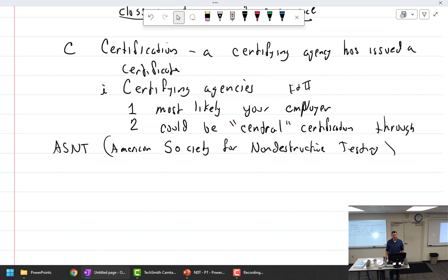Would you find NDT more in general aviation or in every type? Across the board. I never worked for the airlines, so I can't speak to that, but it seems like they're doing an awful lot of it. I was in general aviation and spent a lot of time doing it. But I did engines, so the rest of the airframe doesn't get a lot of it, except higher stressed parts, carry-through spars, things like that. They're now getting ultrasound, eddy current, x-ray, as everything gets older.